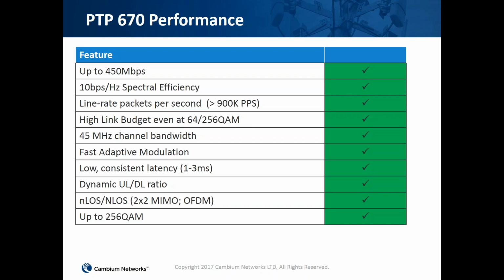So we also have fast adaptive modulation. We have 13 levels of modulation scheme starting from BPSK to 256 QAM. This is useful if, say, in your environment your noise level suddenly goes all the way up because of another radio or other interference. Our adaptive modulation takes all of this into consideration and drops to a level so that you always optimize the maximum throughput that you can over the network. This adaptive modulation works really fast, so you don't have to manually come in and find that the network is down or the link has low throughput.